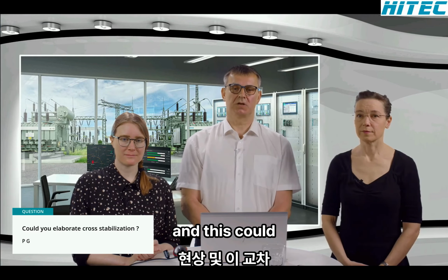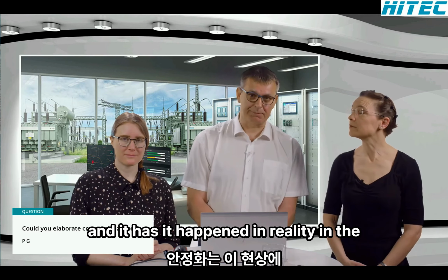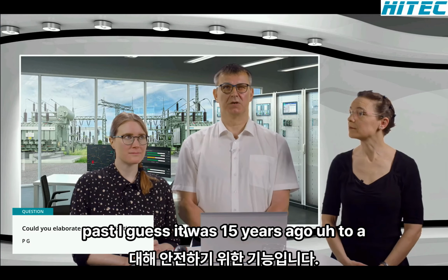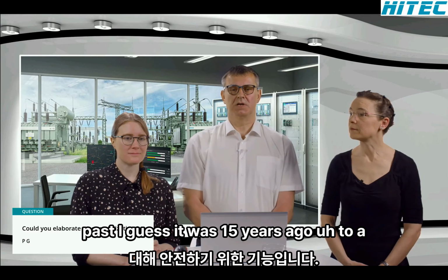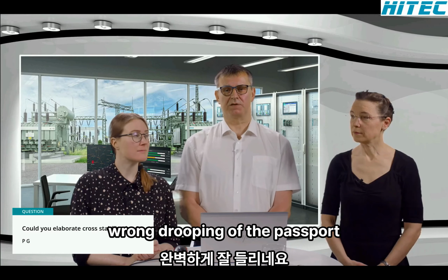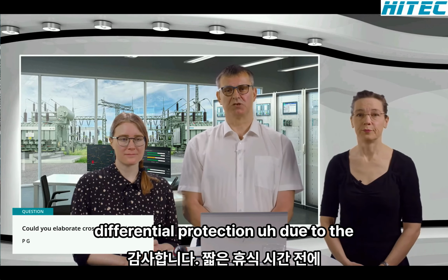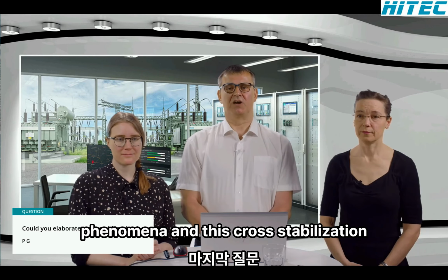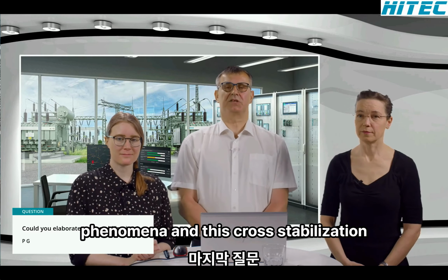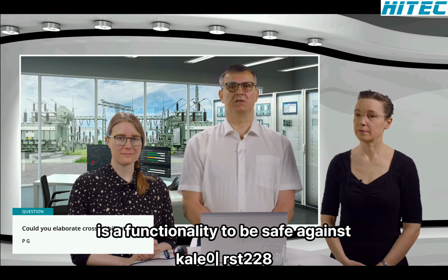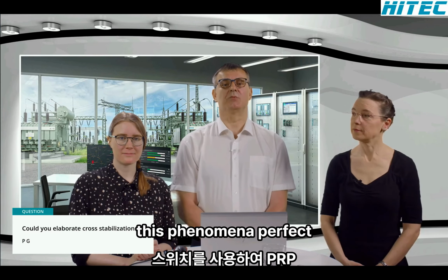And this could, and it happened in reality in the past, I guess it was 15 years ago, lead to a wrong tripping of the busbar differential protection due to the phenomenon. And this cross stabilization is a functionality to be safe against this phenomenon.